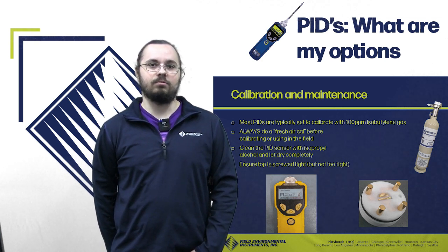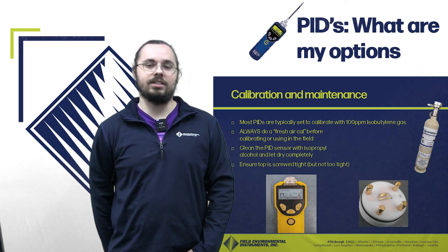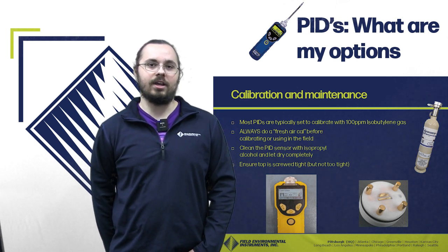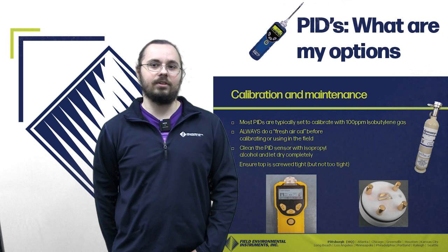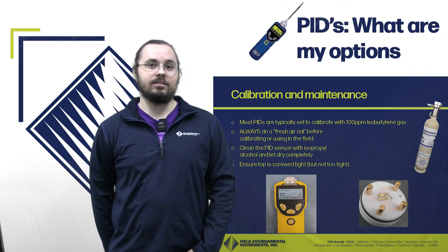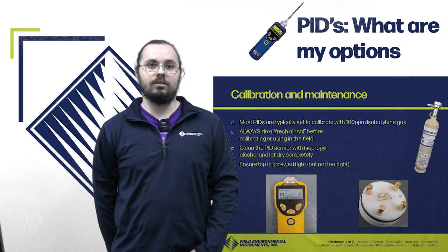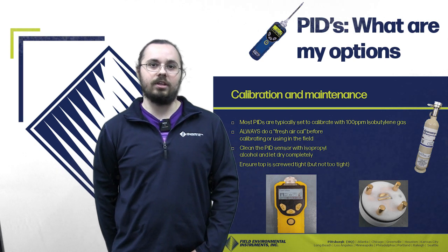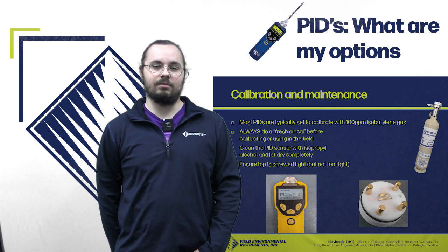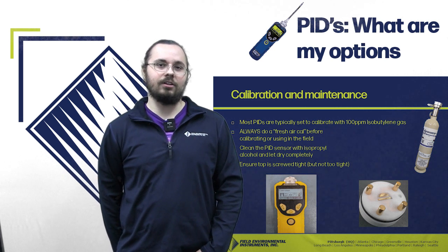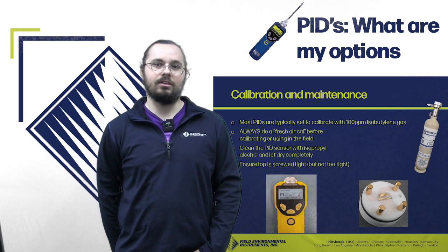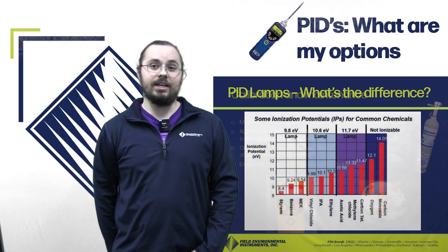Trace amounts of isopropyl do contain VOCs and can lead to some sporadic readings in your unit if it is not completely dry. Last step, be sure to ensure the top part of it is screwed in tight, but not too tight. You want to make sure the gold legs on the PID sensor there make solid contact with the rest of the unit.